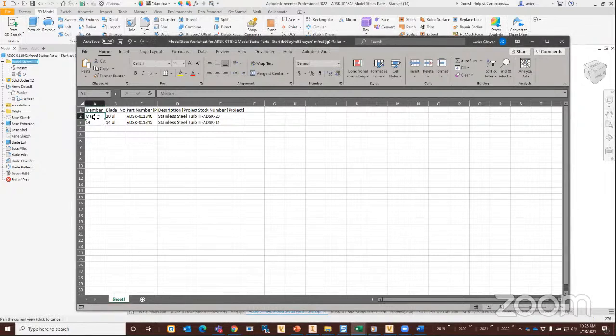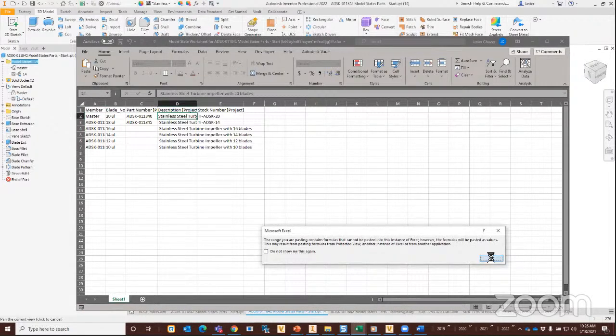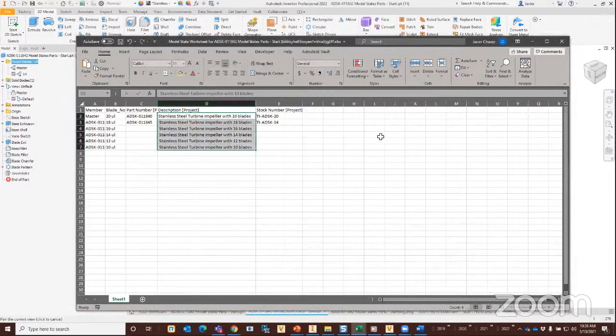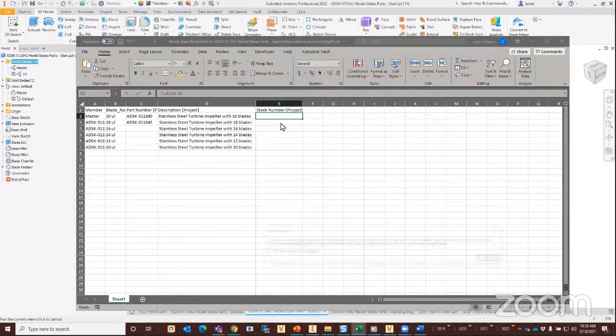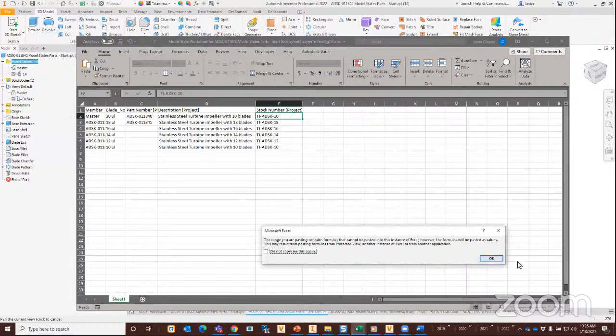And to clarify too, Javier, these aren't like separately saved spreadsheets, correct? These are specific to the part, so they don't have to get checked into Vault separately or anything like that. Correct. The spreadsheet lives within the file, so you don't have to go and manage it there. Yeah, it's similar to other Excel exports in the Autodesk environment too. Yeah, so it's specific to the part. Right, and iParts are basically the same thing. They get treated the same way.